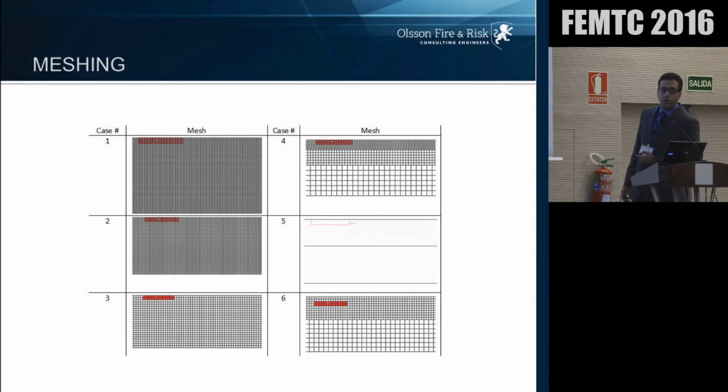This is 41.66 millimeter, and the reason why we have this weird number is simply that I picked the 250 mesh as a standard mesh, and I started to divide that by 2 and 3. So dividing the 250 by 3, you'll get that fine mesh, and if you divide it by 2, you'll get the second option mesh, and then this is the 125 mesh, and this is the base case mesh, which is 250 mil. And on here, we start to refine our mesh in different layers.